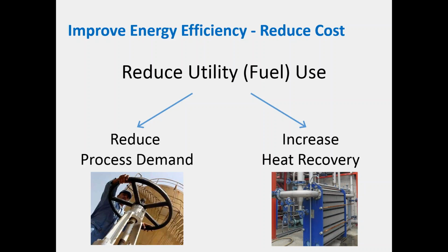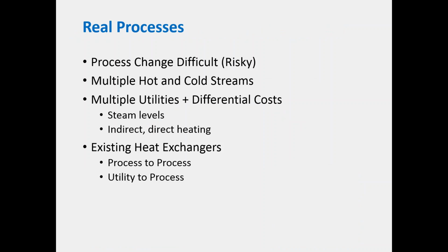And so really, this is the first thing you begin to look at when you're looking at process heat reduction or demand reduction: how can we increase heat recovery. That is usually the best way to begin, but also ask the question, can we reduce the demand by changing the temperatures? But increased heat recovery is usually the first place to look, although it can be challenging, but there are some methods that can be used.